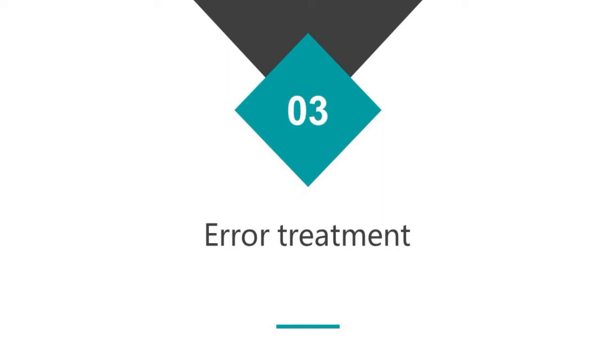And then we can go to the third part. The third part is error treatment. Error displays could just happen at some conditions that may damage the solar system or even damage the VFD. All the error displays start with the character E, such as E.LU, that is low voltage error. The errors could not be reset automatically like alarms. Just now we know alarms could be reset automatically, but errors cannot. You must clear the fault and then press the stop or reset button to clear this fault.